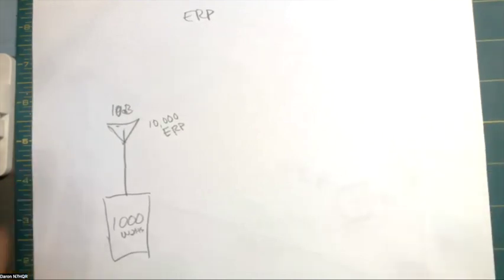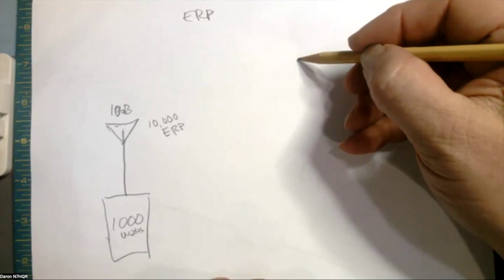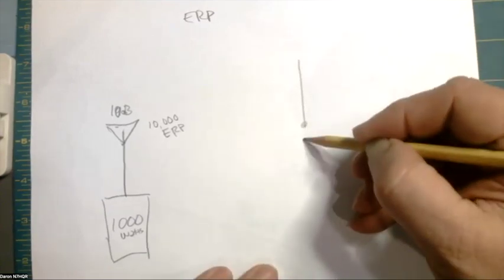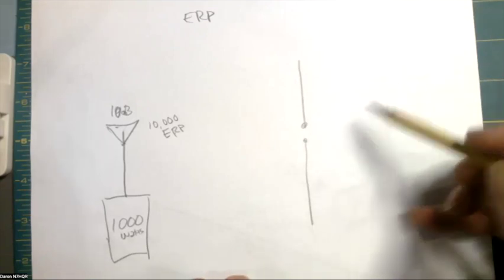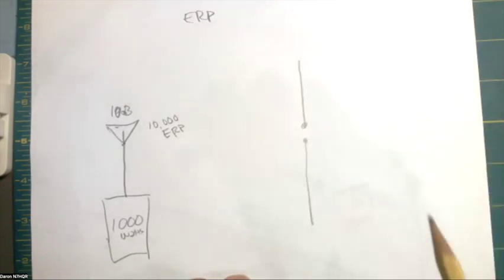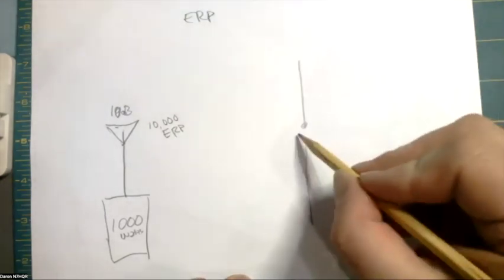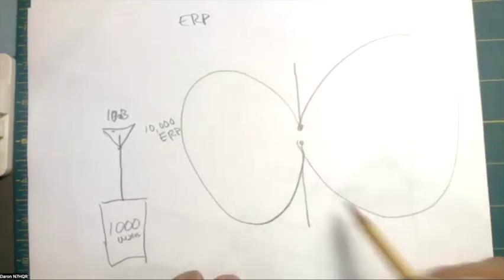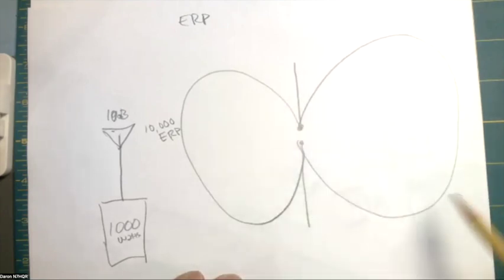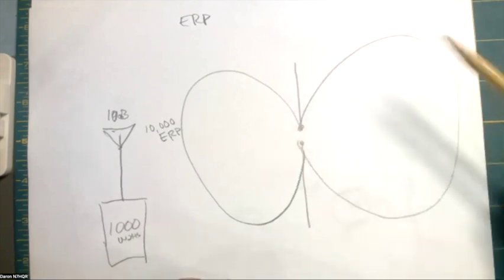So does that mean you can build an antenna of whatever gain you want it to be, within reason? Within practical limits, yeah. So I'll do my horrible illustration here. This is our dipole, and if you can imagine we're looking at it as if you're holding the dipole out in front of you, the antenna pattern looks like a giant donut, except it's a little more even than that. So it's like a giant donut all the way around the antenna, if it's a low gain antenna.